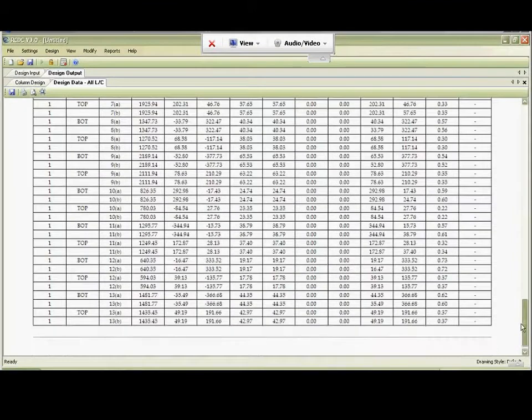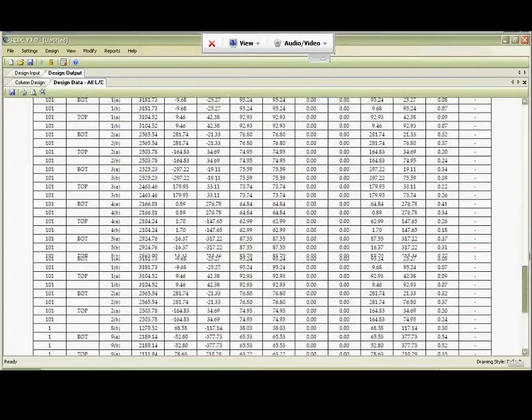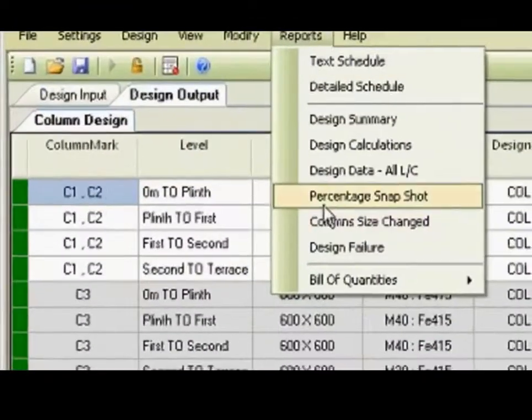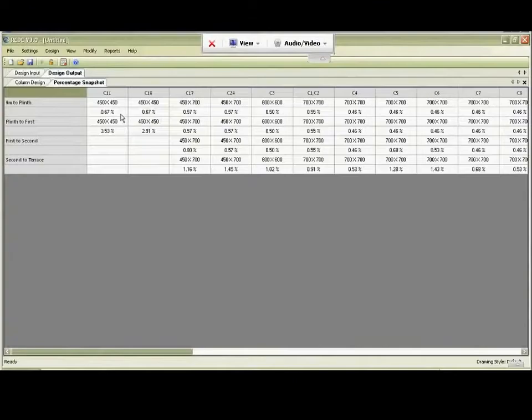So you will see that a lot of them are very close. There is something which is 0.58 here, 0.65, 0.55. All of these are very close, higher interaction ratio ranges, which would govern the design of a column. And this information is sometimes sought by proof consultants to prove that you have designed for all load combinations. So this information can be sent to them. There's some 0.73, 0.72. So it gives you the entire great detailed design output.